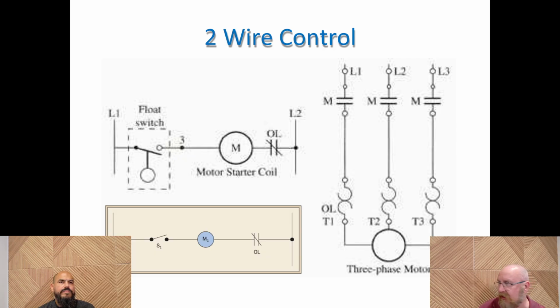Depending on the size of the motor, the bigger the motor is, the more you're going to want to protect it. The cost goes exponentially higher, and the complexity of replacing it potentially could be also. So you'll see overload relays used a lot. You will see fuses, circuit breakers. Depending on what you're talking about, you may see them in line, and we'll talk about that a little later on in this slideshow. But protecting your motor is an integral part of controlling your motor.